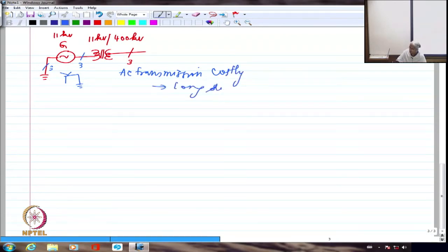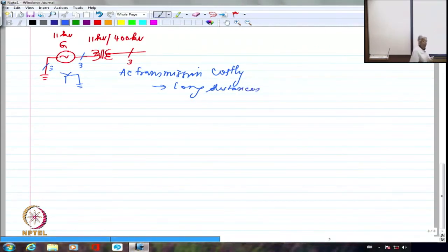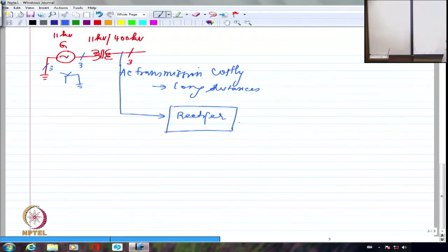So now that we have rectifiers and so on, everything is available with the power electronic converters. What is normally done is, whatever is available in the form of 3-phase is connected to a rectifier. And the rectifier obviously has to withstand 400 multiplied by root 2 kV, because 400 kV is RMS. Each of the devices has to withstand 400 times root 2, and I have to put a factor of safety, in all probability 1.25 or 1.2, so it is going to be way too high. There are no devices available for 400 kV multiplied by root 2 multiplied by 1.2. That's not going to be possible.